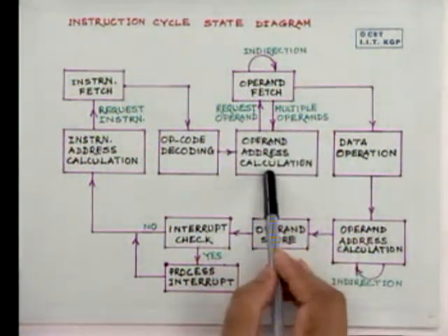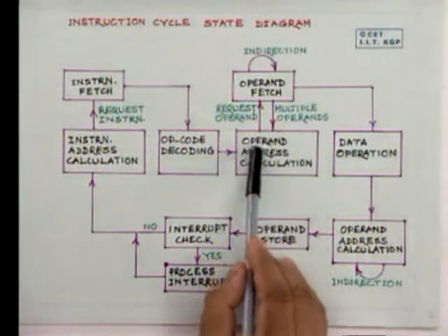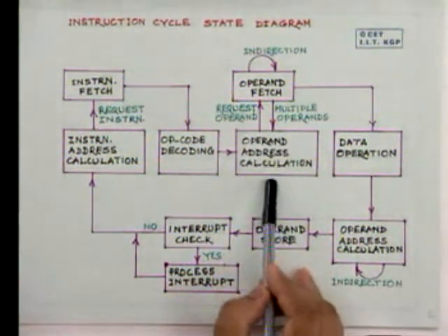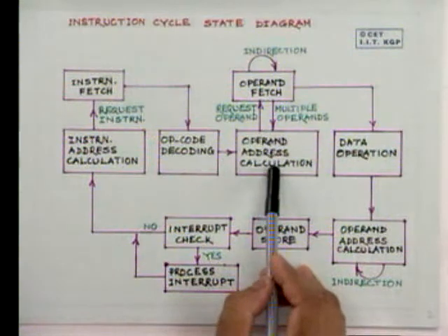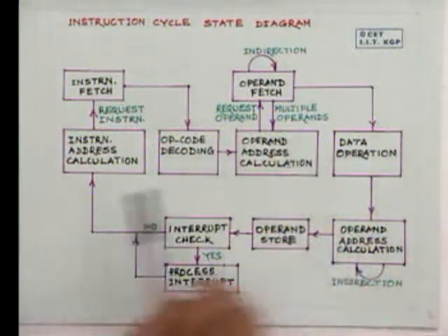operand address calculation starts. Here we write operand address calculation because, as we have seen by this time, there can be many addressing modes, and many addressing modes may need the computation of the address, for example, displacement addressing, based addressing, etc. It basically needs that computation of the address, though it is done hardware wise, but that hardware control operation has to be performed here.